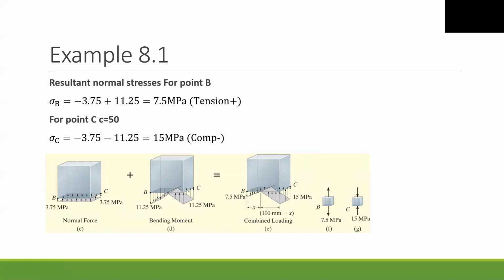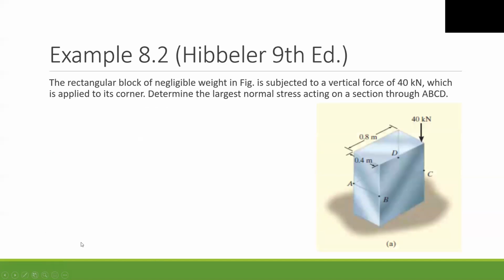Also, in some questions, if you want to find the zero stress line, there's a linear relation between the two stress distributions, the equality of triangles. You may remember that by using the equality of triangles, we can find the zero stress zone. I think this solution is not written in the question, but if the question needs the location of the zero stress point, this is easy.